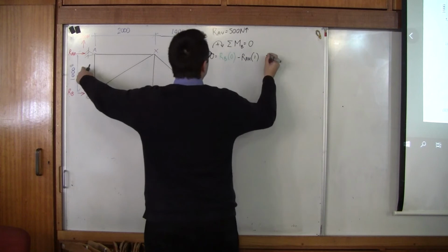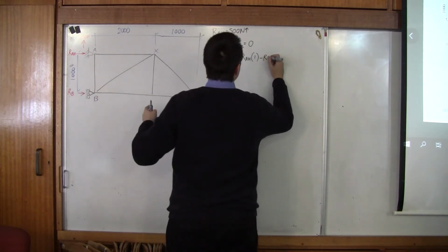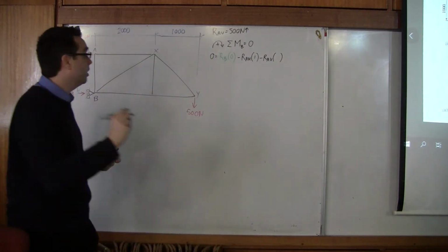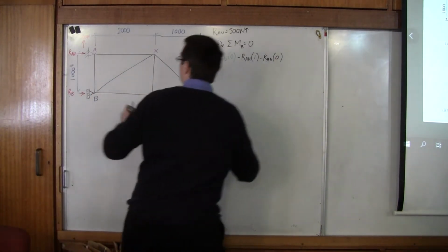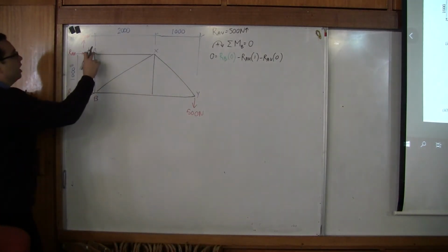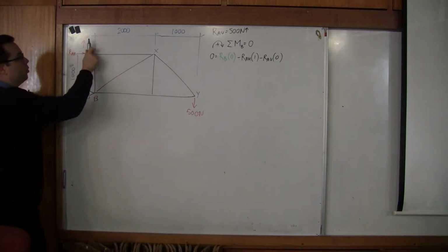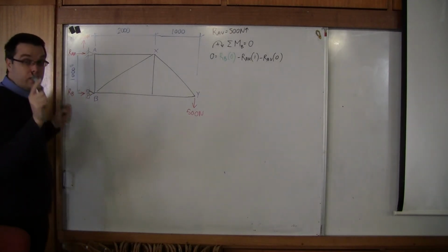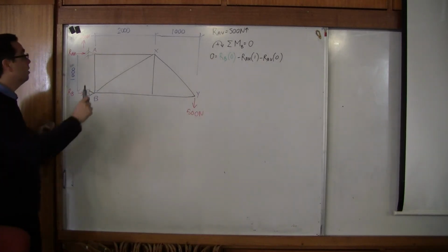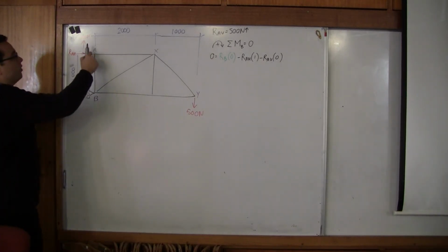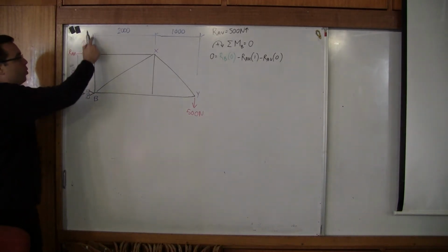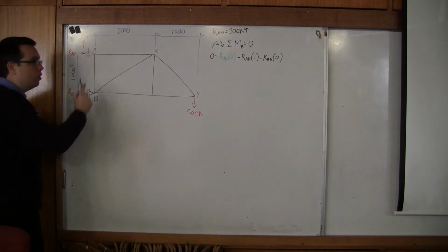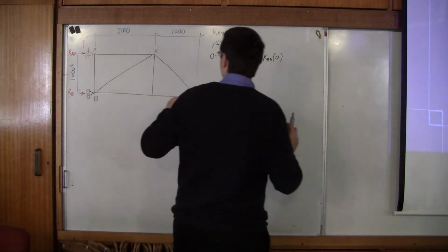RAH. The next force is RAV. What is the perpendicular distance of RAV? 0. 0, excellent, thank you very much. Because that line passes through, it's actually being applied here. Even though I've drawn it here, the force is actually being applied here, and it's going to pass through that same location. That's a bit of a confusing thing for people, and I'm glad you answered that. There's a force, even though I've drawn it here, it's actually going through point A. And so point A lines up with point B so that it won't have any perpendicular distance. Excellent, thank you very much.